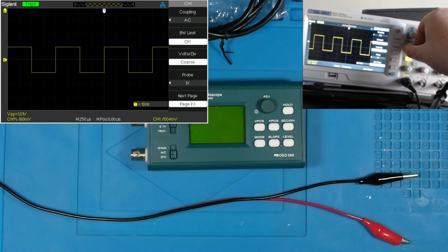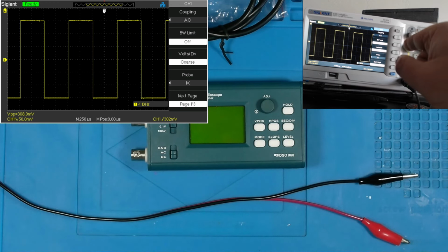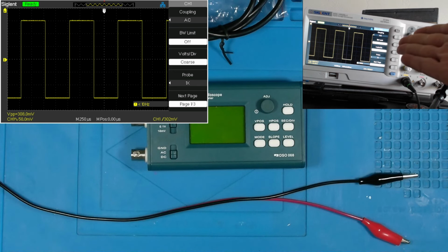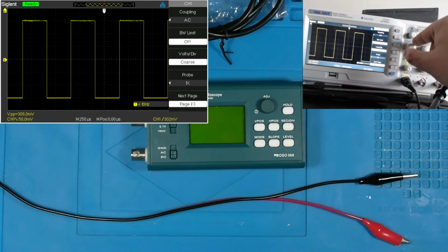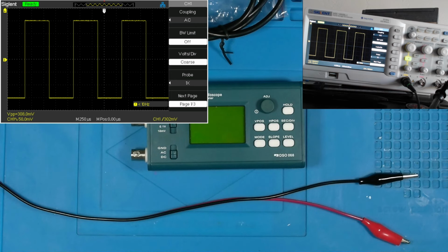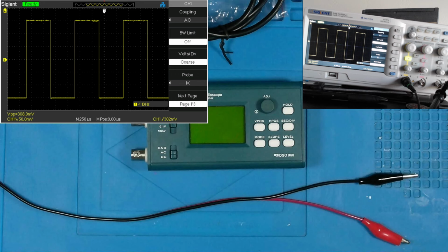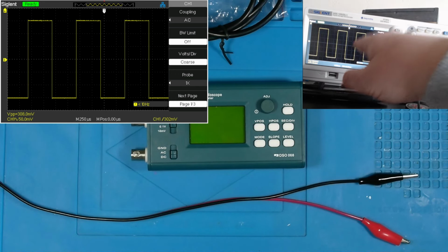What this is allowing you to do is take greater voltage measurements through your oscilloscope probe. So if you have something that you can't bring in to full scale, vertical, full scale on your oscilloscope, you switch it to 10 by, and then what that does is that attenuates that signal by a magnitude of 10, so that way you can now get it onto your oscilloscope display.